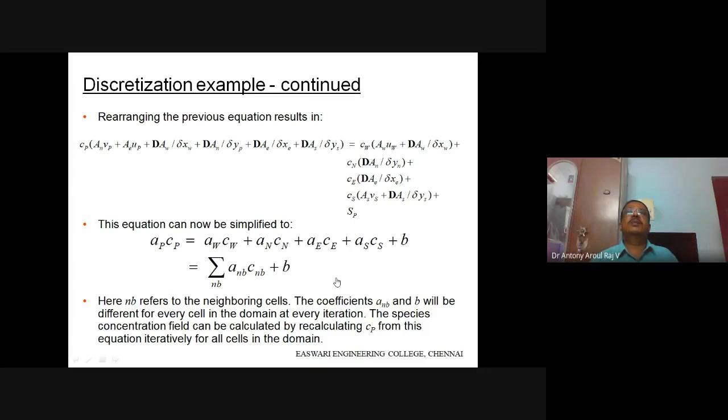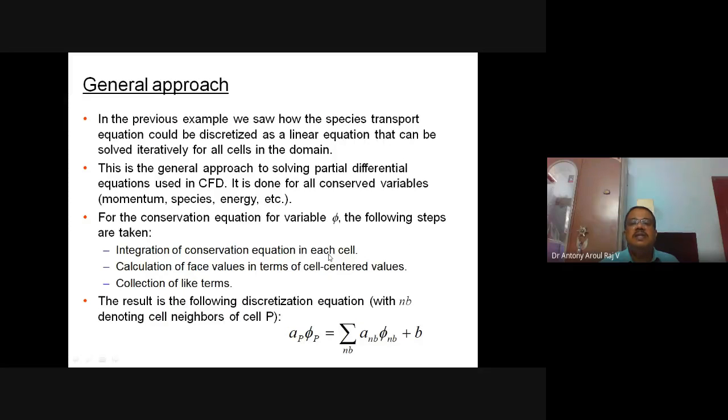Similarly, if you are going for a two-dimensional problem, the information is available along the lines at the boundary, and those are transported inside. If you are going for a three-dimensional problem, this information is available along the area, and it is transported inside the domain, inside the volume. How is it transported? It is because of this mesh connectivity. If you understand this mesh connectivity, it is very simple for you to understand the numerical method as well as CFD.